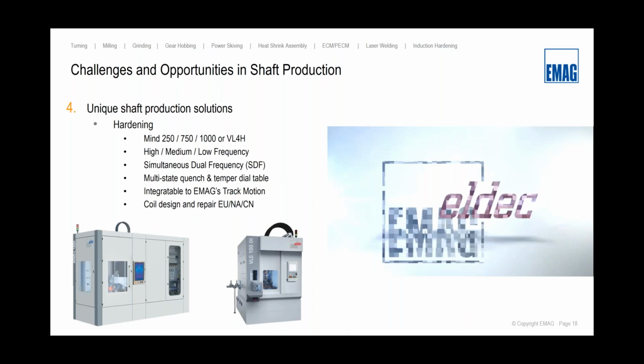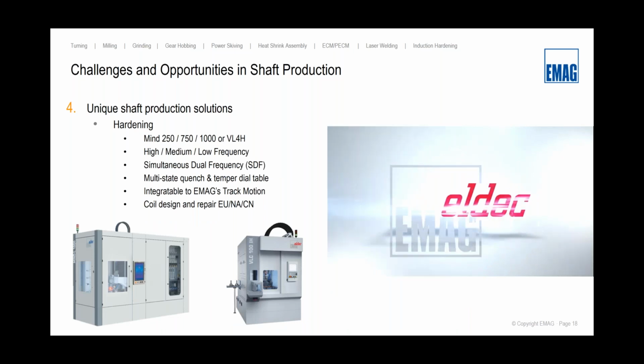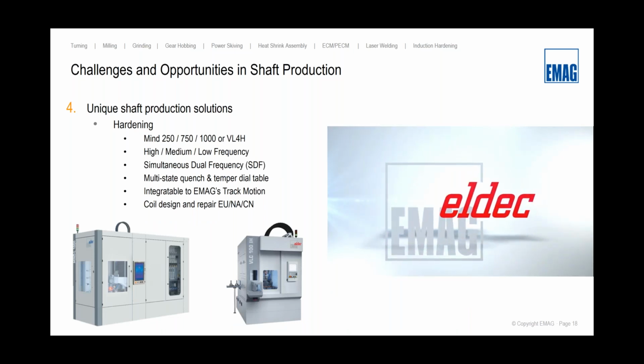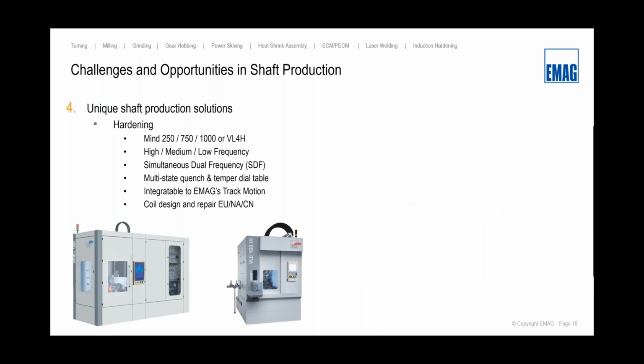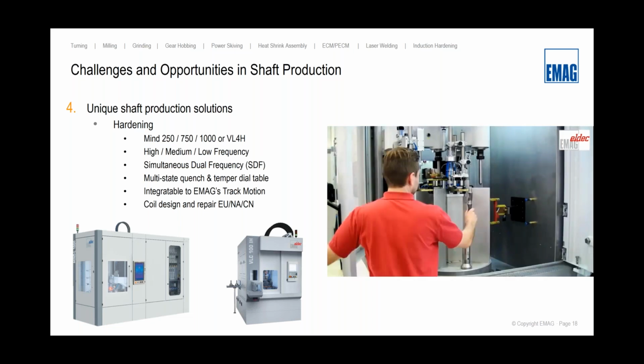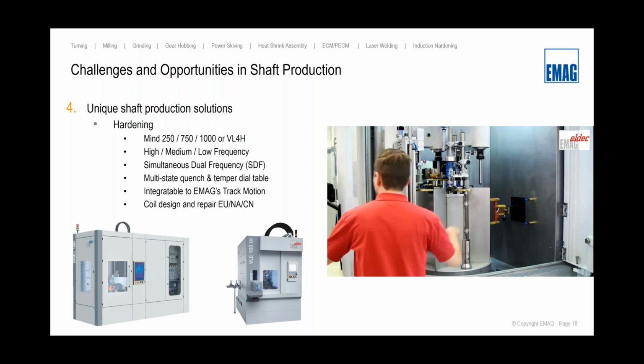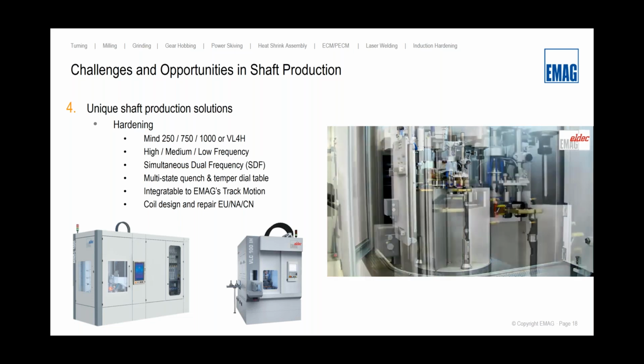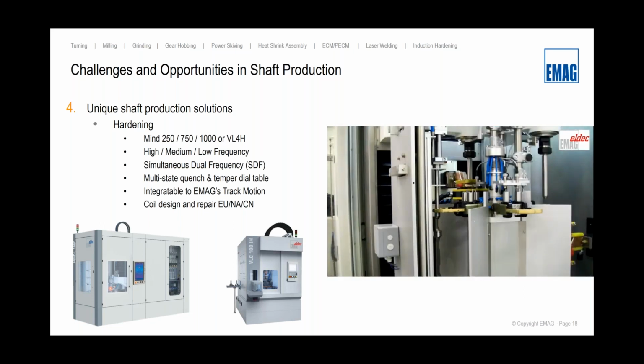Next step in the process would be the induction hardening. And I would say likewise, the LDEC solutions are geared around shaft type components. We really have solutions for low, medium, or high frequency type applications depending on the demand of the depth of the hardened zone. But we also feature simultaneous dual frequency, which allows us to achieve a true contour of a gear profile, as an example.